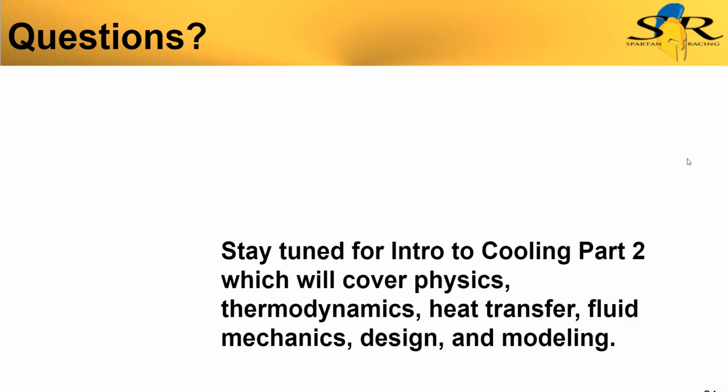In that case, you would want to find the lowest pressure part of your system, and that's going to have to do with the pump and where your radiator cap or pressure cap is, where those two things are in relation to each other. You can find a low pressure part of your system to put that component in, and hopefully it aligns with your packaging and plumbing.